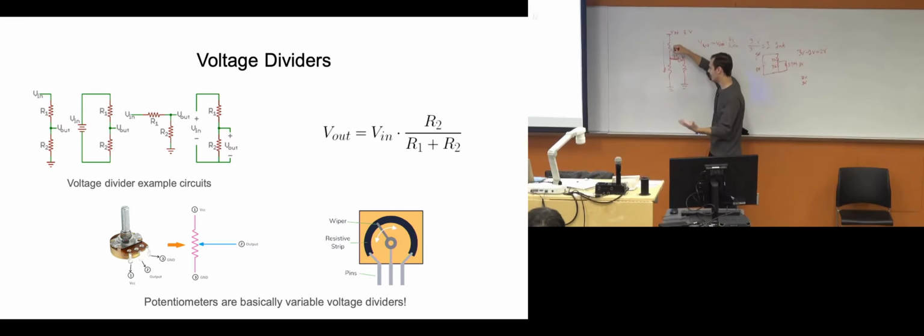So current, you can kind of think of it like a diode, but it has a bunch of transistors and stuff. But essentially, current can flow this way. Current cannot flow this way. From this resistor's perspective, it's like an open circuit, and it's just getting 3 volts from somewhere, right? So this doesn't affect our output voltage here.